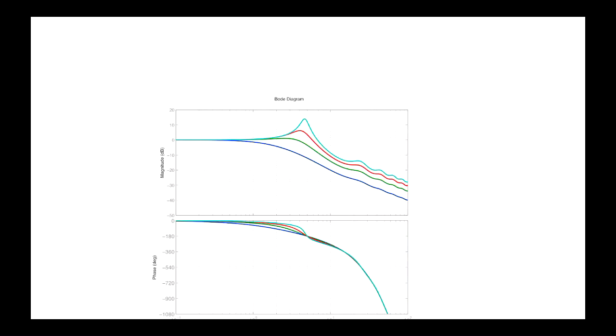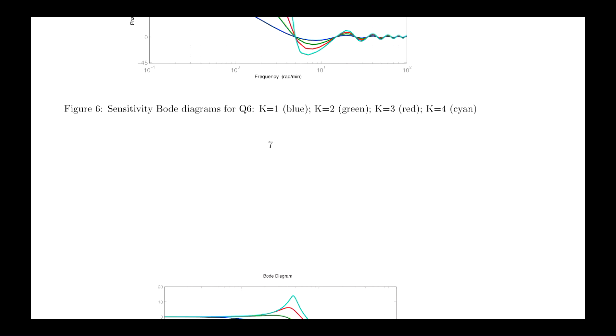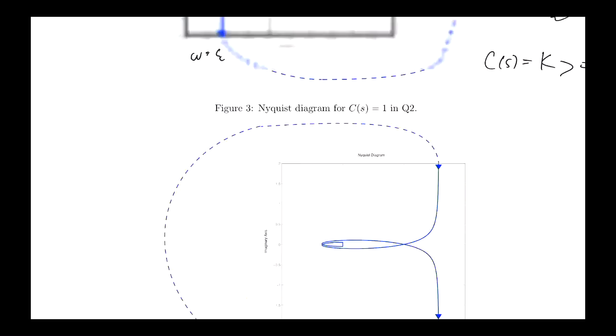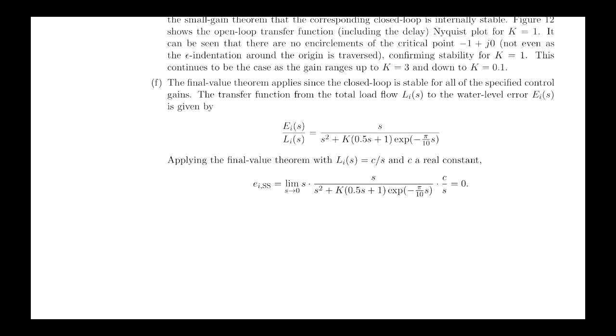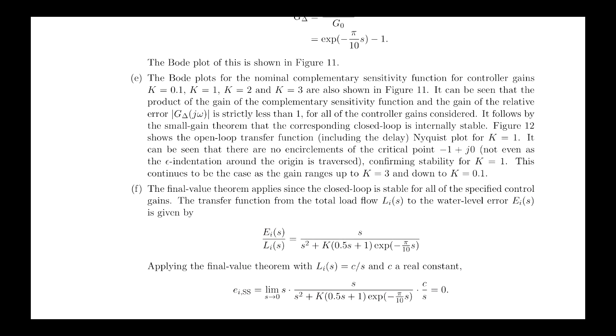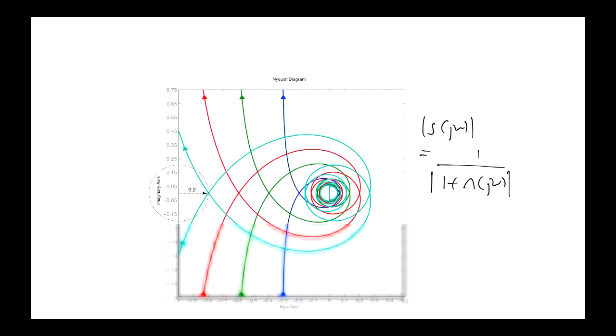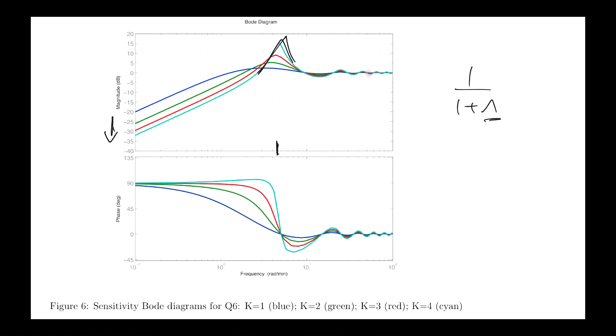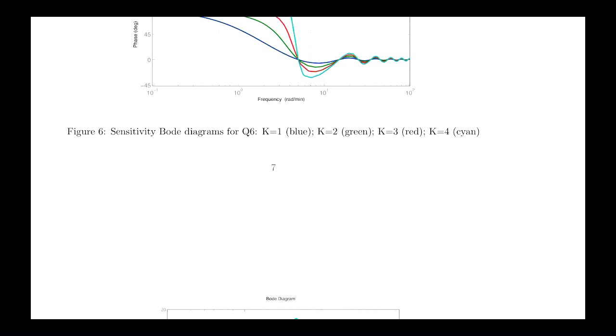So if we look at the closed loop, the transfer functions look like this. They've got this irrational part in them. So it's not just a finite number of poles and zeros that we're dealing with when looking at the Bode plots. This term here causes those sorts of wiggles in the plots, particularly at high frequency. Okay, so don't get confused by that.